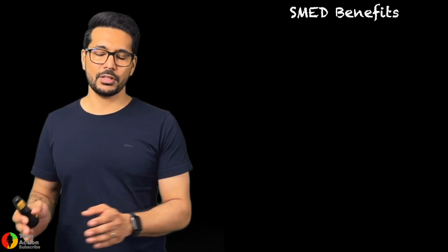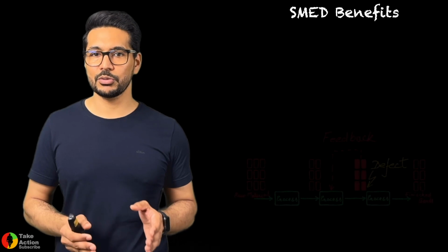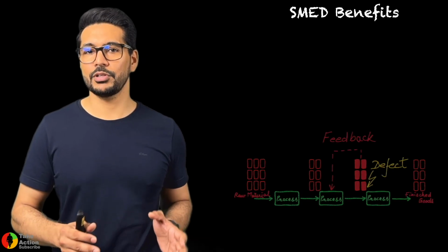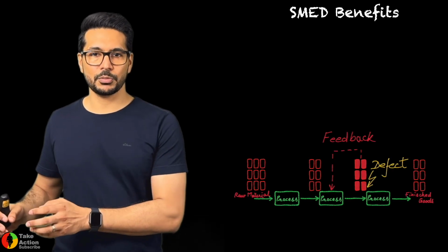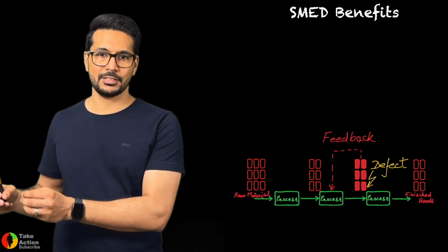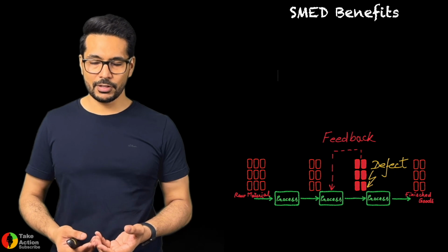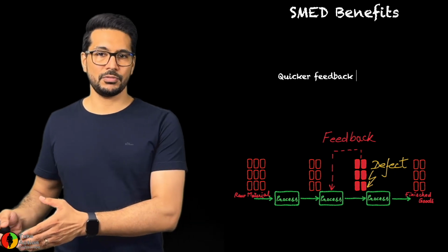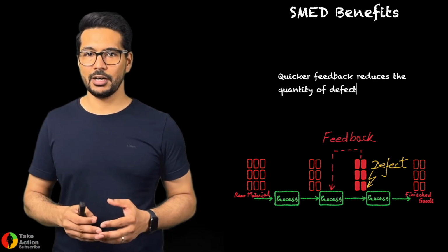With that, the probability is very high that all 100 parts are affected by this defect. Now, with the setup time reduction, if we reduce the lot size by 50% and we send smaller lots to our customer process, then if the customer process detects a defect in the part, definitely the maximum affected parts will be 50 and not 100.